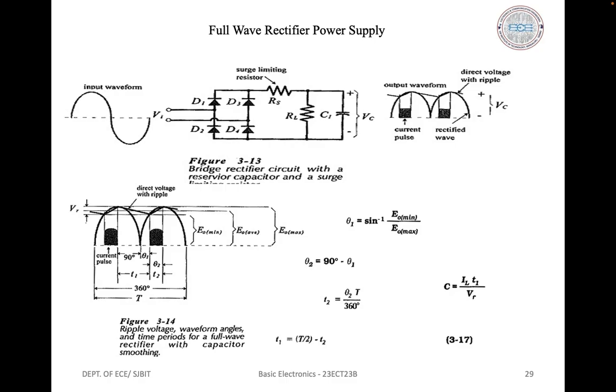Similarly, with the correct value of T1, the repetitive current IFRM can be determined from IFRM is equal to IL into (T1 plus T2) by T2. The average forward current passed by the bridge rectifier circuit is equal to the load current, but each pair of diodes supplies current for no more than a half cycle of the input wave. The other pair conducts during the other half cycle.